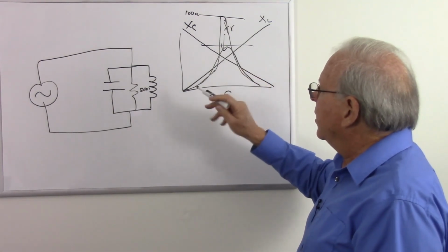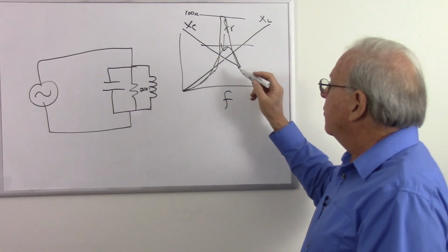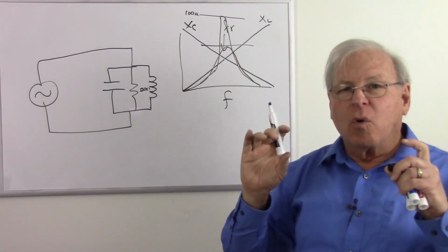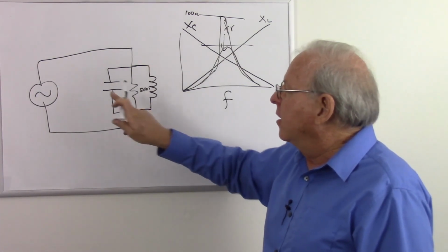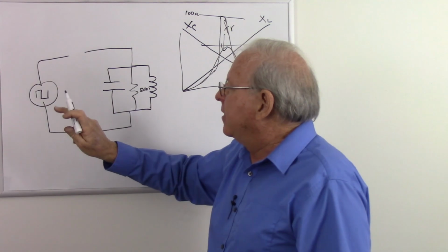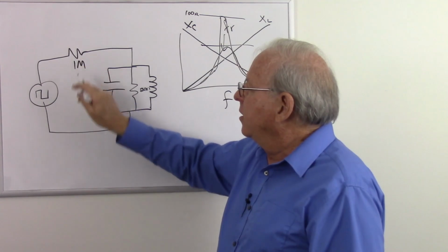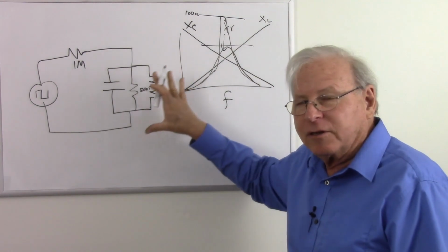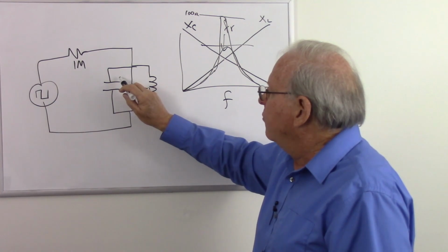So using it as a filter, we can manipulate the Q to see how wide of a band of frequencies we want to filter. And at that resonant frequency, this circuit wants to, quote, ring. It wants to resonate. So if we put energy into it, and like I said, if we turn this into a square wave to make that dramatic, put in some resistance to isolate it, lots of resistance, because if we don't put the resistance there, the voltage here is the same as the voltage there, so it will not ring, it'll be all damped out.